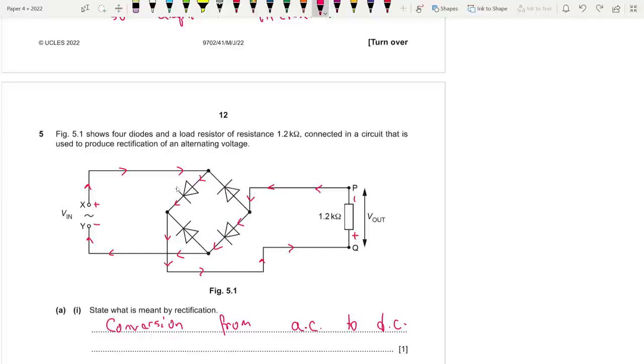Okay, now when the current switches, we're going to use this and this. I'm going to show you how. If this was the positive terminal and if this was negative, how would we be doing this? I'm going to show you that it remains the same at the end. So current would come out from here. It would go here. We take this terminal, right? See, here you go. At the end, this is still positive. This is negative. Then we come out here, go down here, go up here, and come back over here. That's it. So it doesn't depend on our input really. Even if our input alternates, we are going to have same outputs in our terminals.